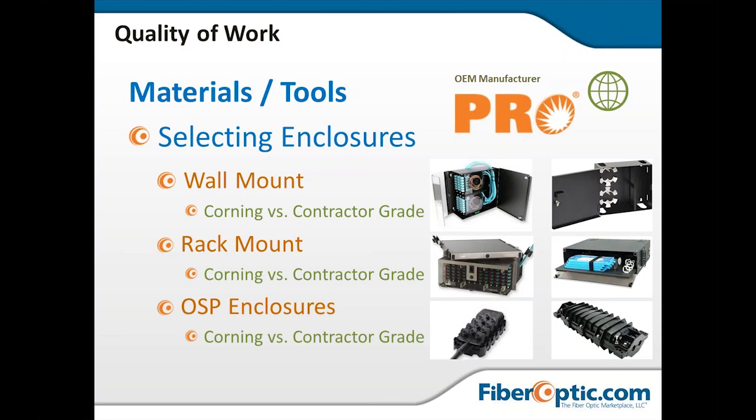You see that Corning one at the top. All that light colored or multiple colors wrapped up in that circle there, that is 900 micron fiber. You really want all that 900 micron fiber to be contained within a splice tray or a cassette, which it is there, and never have that exposed in any way to a zip tie, or allow that to be touched by a door or swinging object. That outside jacket actually has Kevlar underneath it to protect it from those types of penetrations.